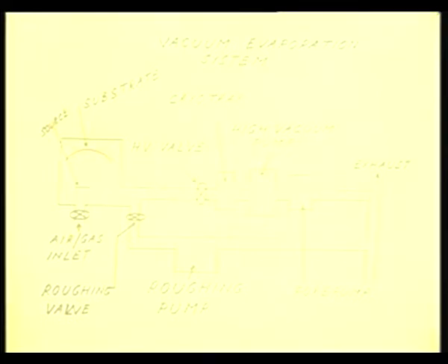After this level of vacuum has been achieved, you may want to slightly heat the substrate. That is an optional process. Usually, heating of the substrate is done so that better adhesion of the films is obtained. You are depositing a metal film on the semiconductor, you want good adhesion, and good adhesion can be obtained if the substrate temperature is raised. So, that is an optional step of heating the substrate. And finally, of course, you will evaporate the metal to form the metal film.